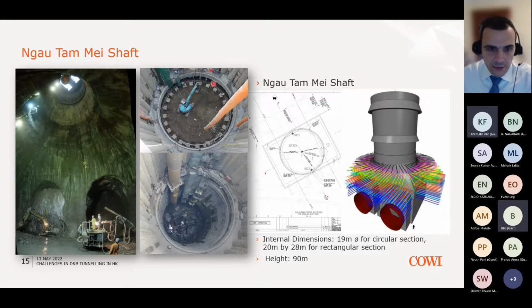What you can see here in this photo in the middle is a photo from the ground surface looking down the excavation, and you can see that up to this point the shaft is being supported by these piles, and we weren't responsible for this support. Our responsibility lies below these. These piles were used to support the overburden material, so the soil. So that's the transition here, the end of the piles, the transition from soil into rock.